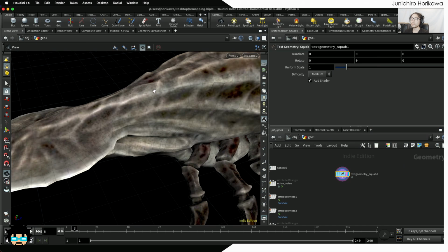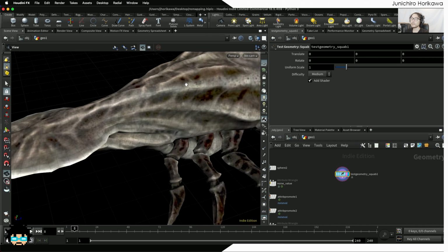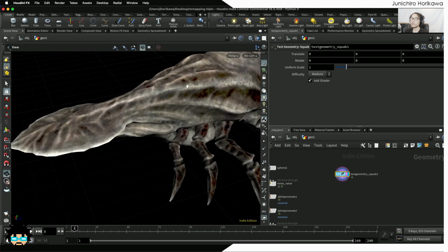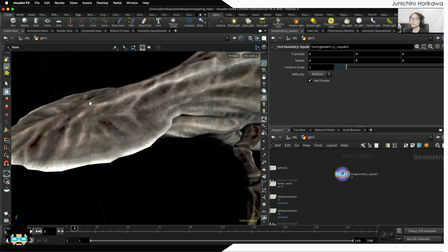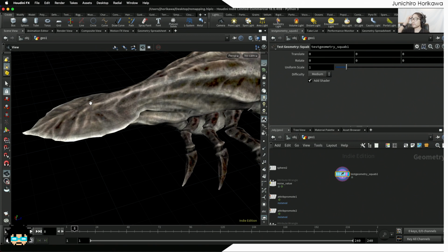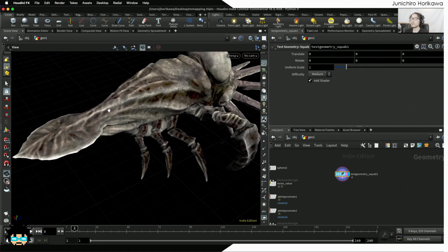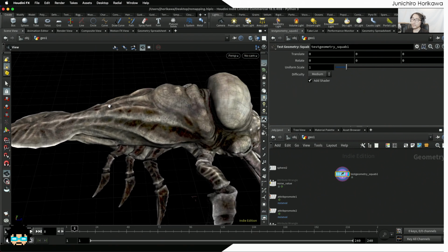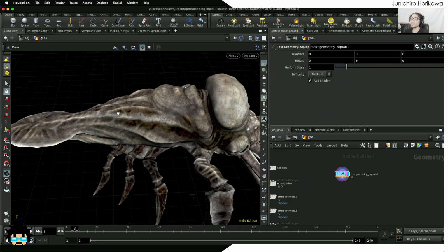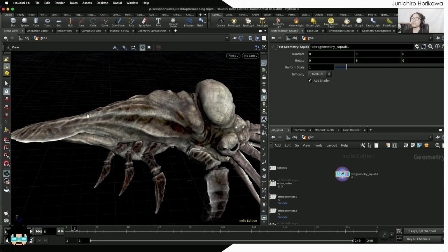So from here to here, maybe the distance is 1, this here is equal to 2 and 3 and so on. So from this point position, I'm going to use the function called surface distance to calculate this distance on this surface and use that value to change the waviness or the wavy height